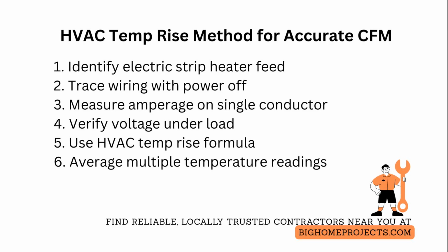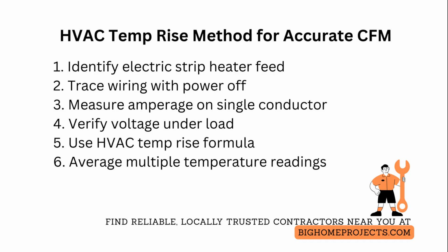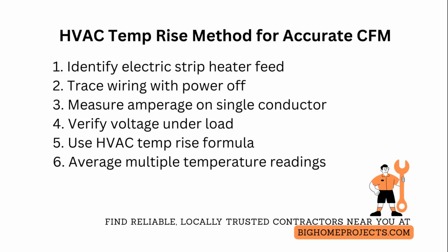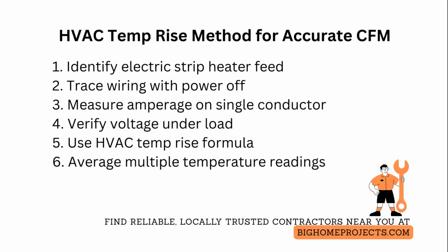verify voltage under load with a true root mean square voltmeter, because supply voltage drop will skew wattage and therefore cubic feet per minute. Use the HVAC temperature rise formula: CFM equals heater watts divided by the product of 1.025 and the measured temperature rise in degrees Fahrenheit, and record